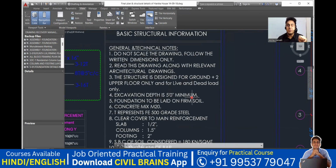Excavation depth is 5 feet minimum. That means minimum 5 feet of excavation has to be done whenever you're putting your footing, and the foundation is to be laid on the firm soil. That means very hard soil. Whenever you get there, you're supposed to put your foundation, and you're supposed to make use of M20 grade of concrete, where M stands for mix and 20 is the characteristic compressive strength of the concrete.